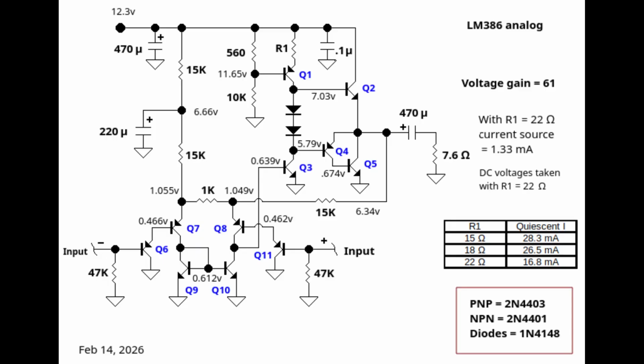Typically, as a radio builder, I would use a resistor for a collector load at audio frequencies. In linear ICs, rather than load resistors, often enough, active loads, which are termed current mirrors, get used instead. The current mirror supplies the collector load and load biasing elements, plus gives a single-ended output drive for Q3, which is the main signal voltage amplifier. So in summary, Q9 and Q10 form a current mirror.